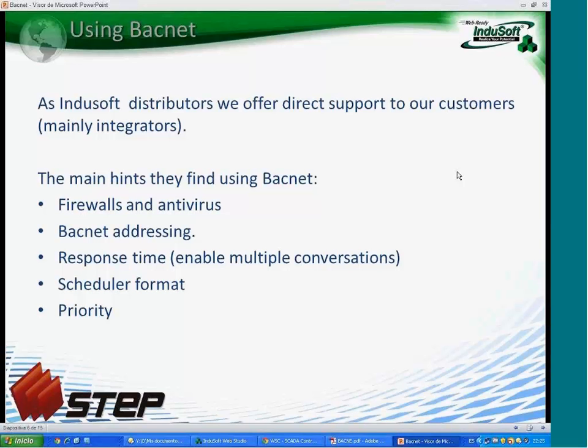But if in the same building you have the SCADA and small local panels, you have to check the priority the local panels are using and arrange the priority of InduSoft to be the same. Otherwise, only the highest priority will send the set point or the order.